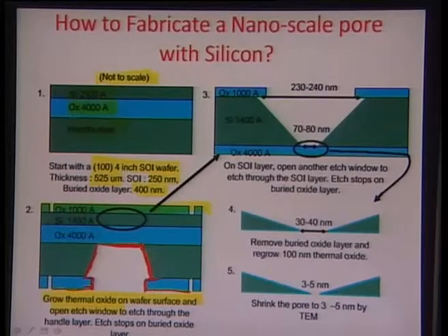Okay. So you have to use an etchant combination, one which is selective to SiO2 and one which is selective to silicon. So one cannot etch this oxide once it hits the oxide, however it etches the silicon. So it is etching silicon and selective to oxide, and in the other system it is etching the silicon dioxide and selective to silicon. So you have to follow process 2 first and then process 1, so you can get the right shape over this handle layer. Okay. So the etch stop is the buried oxide layer in that particular case, alright, as you are seeing here.